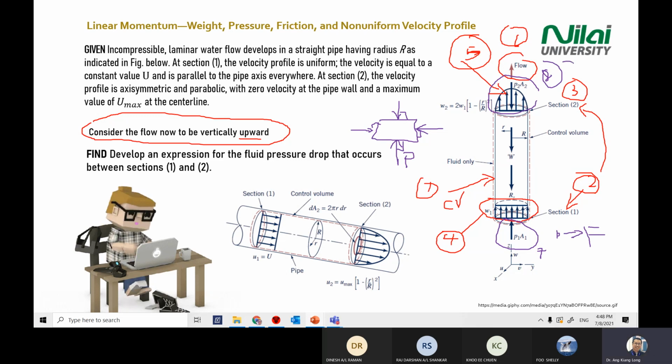These are the areas where students make mistakes, especially on the outlet. No issue on the inlet. All students know how to draw the inlet, but there will be one or two students who forget the direction when they convert pressure into force. They will draw this force going out, and then you get the wrong answer. Next, you will consider the weight of the fluid because you're using water. Water always comes with a mass, and mass will always give you weight. So this is step number 9.